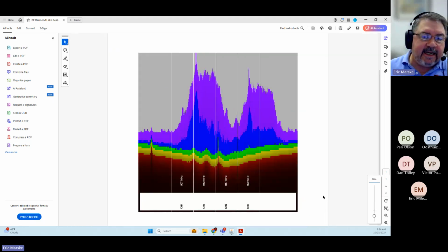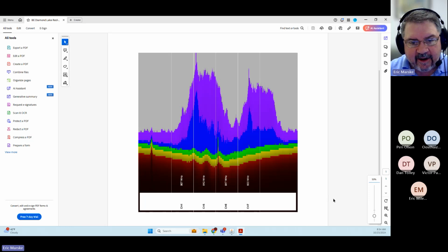What this did is it identified, in the 900 megahertz band, an active transmitter. I've got a small little rubber duck antenna tied to the one here. This was actually tied into the antenna that was installed at the customer site. So you can actually view what that installed antenna is actually seeing. Looking at this, you can see we had quite a bit of transmissions at 912, and there was actually one above 922. This was actually a licensed channel.